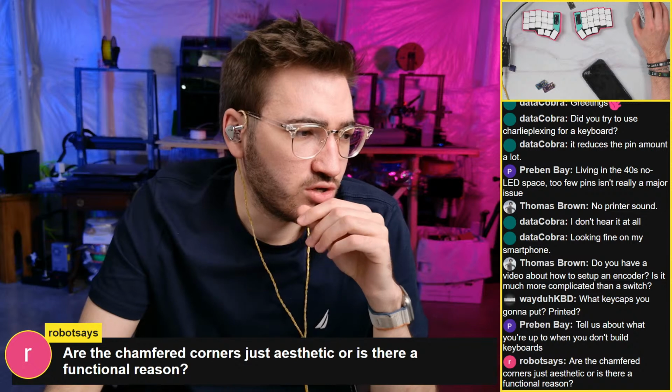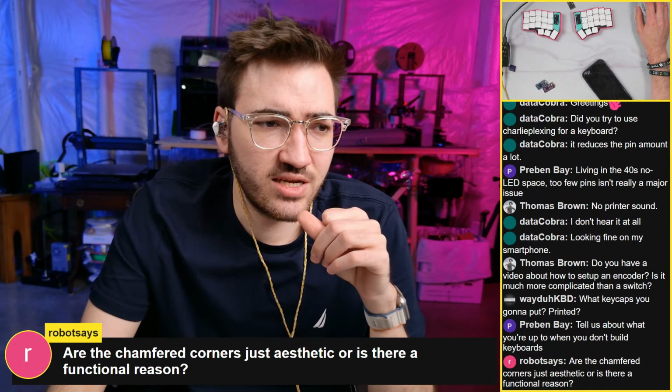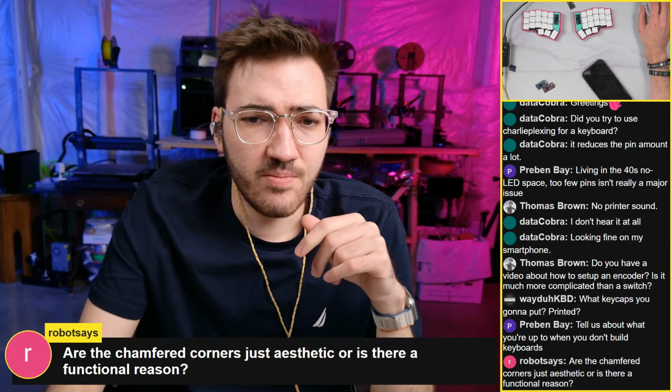Are the chamfer corners just aesthetic, or is there a functional reason? Literally just aesthetic, that's it. Just so it looks good. They are a bit of a pain to print, though, because they can kind of wobble down, because they are printing without support. They normally print fine, but it's just to make it look good. But that actually does remind me, I've kind of tried to do some boards with more sharper angles, because sharper angles print better. Chamfered stuff doesn't print as nice. Or filleted, rounded doesn't print as nice, right? So if you have a straight angle, it prints a lot nicer because the printer can just do that.